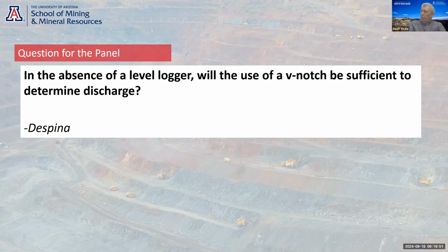Just to go back to the injection testing of diamond holes, I'll pass on some experience from a couple of sites I've just been working on. For the injection test, what we've started to do is a temperature and conductivity log of the hole, then run an injection, making sure the injected water has a different temperature or electrical conductivity to the formation water, and then run the downhole temperature and conductivity log after the test, so you can see which formations the injected water has gone into. That will enable you to assess the depth of the productive fractures. It's worked quite well.